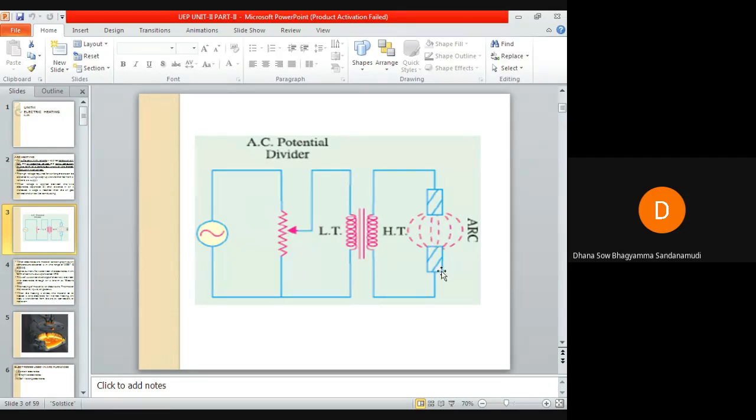When current flows through these electrodes, a continuous spark appears between them when sufficiently high voltage is applied with the help of a step-up transformer. We give a name to that continuous spark: arc. What is an arc? You might have already learned this in your SGP subject. This self-sustained discharge of electricity between two electrodes through air is known as an electric arc.